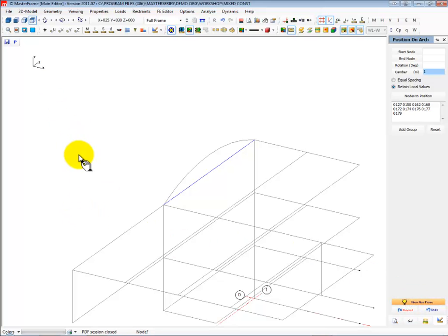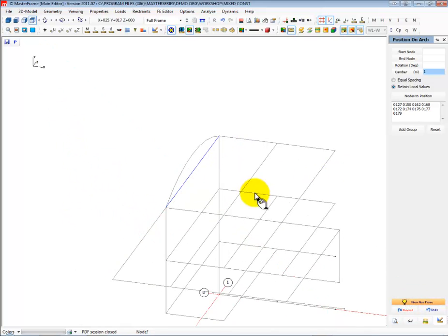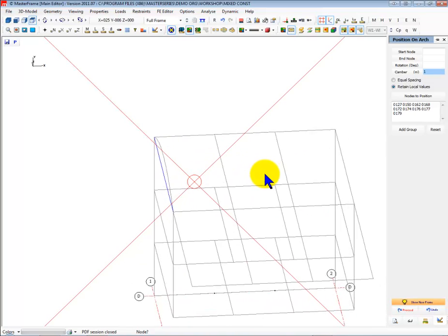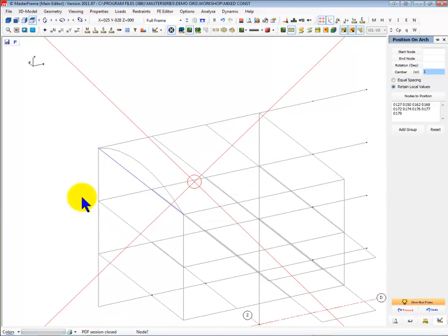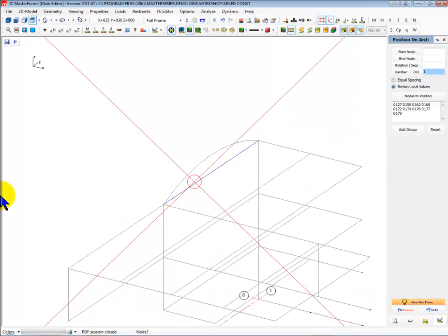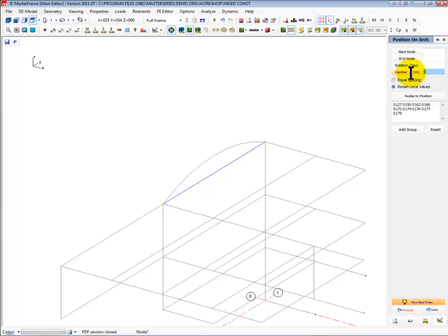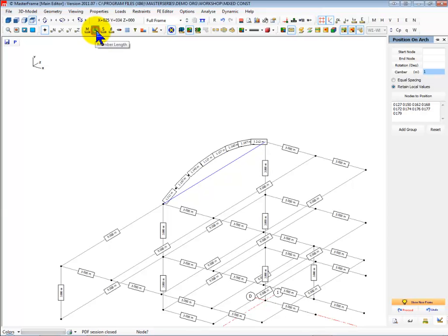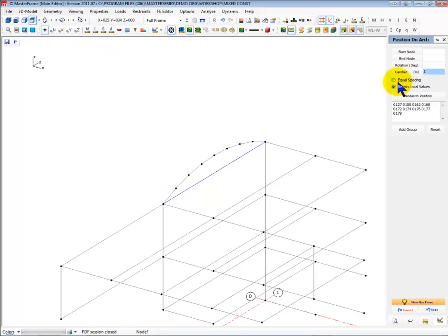And what's happened is that it's done a vertical rotation of our member, because that's what a camber usually is. Now, where's my nodes? So what's happened, if we look at the length of each of these, is that they're all different lengths because they've all jumped vertically upwards. Instead of doing that, I can make them all equal, and watch what happens to the nodes. They just move slightly so that the lengths are all now equal. So that's your vertical camber.